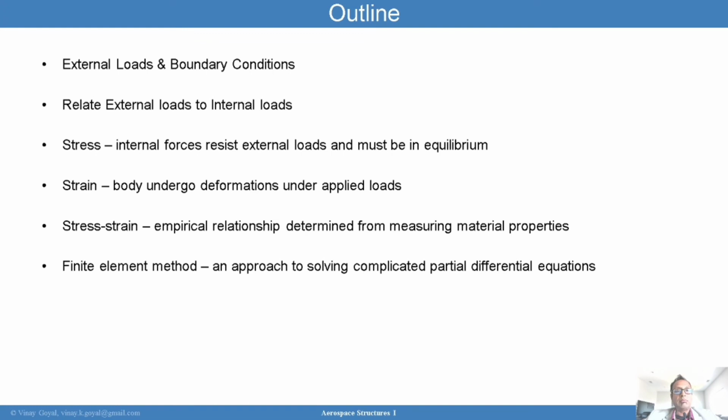Strains are deformations that can be measured, and the structure will experience the strains under applied loads. The stresses can be connected to strains through a constitutive relationship, which can be determined through measuring material properties, and we'll go through that. The finite element models can be used to solve this complicated set of equations we'll be discussing later today.